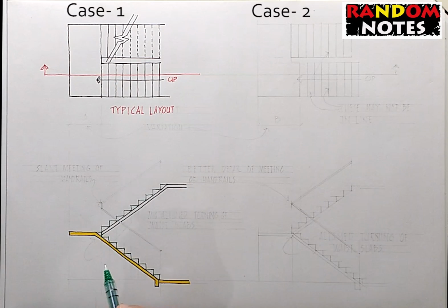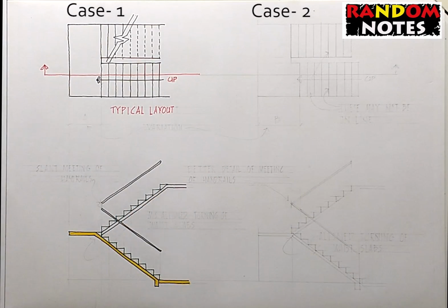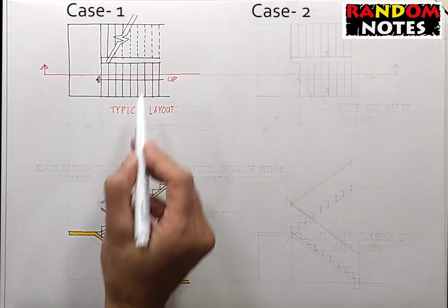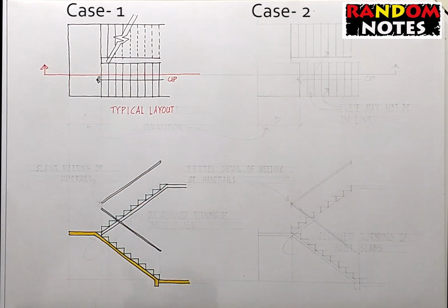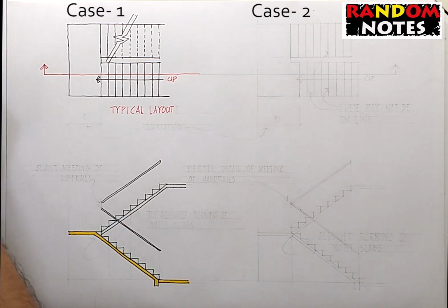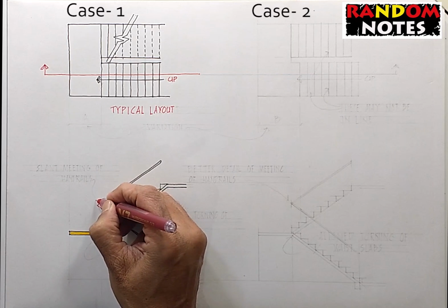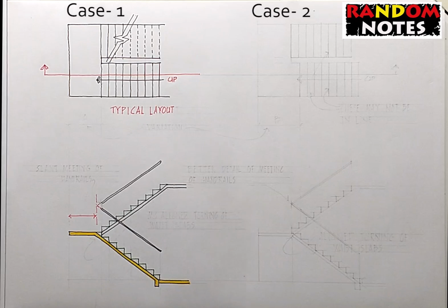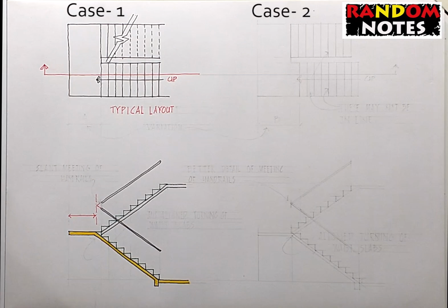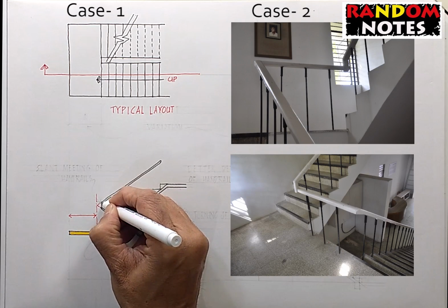We will now make the handrail of the first flight rising up. And the handrail of the second flight. The two handrails rise parallel to the flight and secure the unprotected edges of the two flights. For the two handrails to meet at the same elevation, they should extend into the space of the mid landing. If we do not want to lose the space of the mid landing, then we should either have a connection which is diagonal or which is bent. Some may take this as a bad detail.